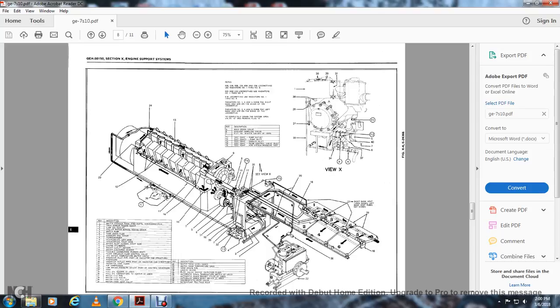Alright, 1 is your water storage tank, 2 is the intercooler, 2 is the tank screen access door, 3 is the lube oil cooler, 4 is the cooler water screen access cover, 5 is the water pump, 6 is the water pump drain plug, 7 is the forward and rear covers, 8 is turbocharger, 9 is interlocking left side, 10 is the interlocking right side, 11 the water inlet header right side, 12 engine cylinders, 13 water outlet header, 14 water discharge header, 15 flexible connections, a rubber boot, 16 fluid amplifier flow control valve, 17 the hot water temperature switch,